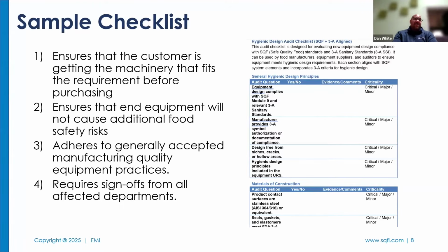Other things that we're seeing too, even from the outside, are the materials of construction. I've seen pieces of equipment show up with non-food grade grease covering it that is extraordinarily difficult to remove. Or it shows up and the exterior is stainless, but the interior of it is all carbon steel. These are things that we all have to check on beforehand. You don't want rusty rollers.